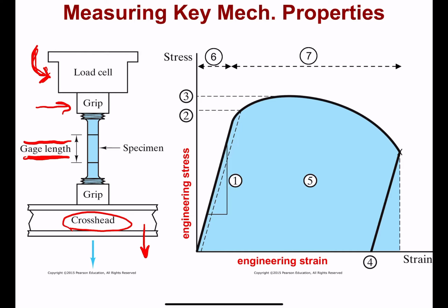Okay, so we've defined stress a moment ago. We saw that that was the force applied divided by the cross-sectional area, A naught. So that is, of course, under no load. So we measure the cross-sectional area. If this were a rod, there might be a cross-sectional area represented by a circle, and that would be our normalizing factor for all the forces applied to our sample. We were going to call this sigma, equal to the force, in this case a tensional force, applied divided through by the cross-sectional area.